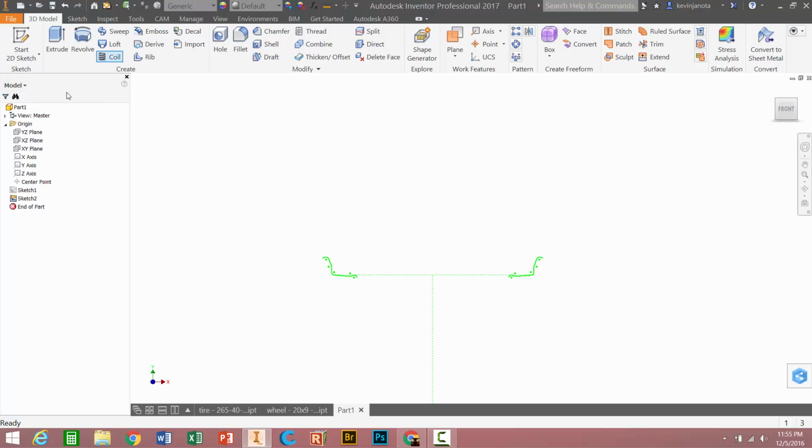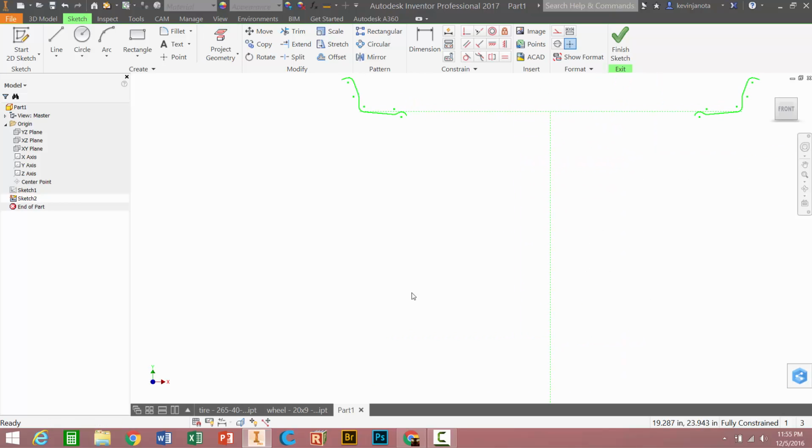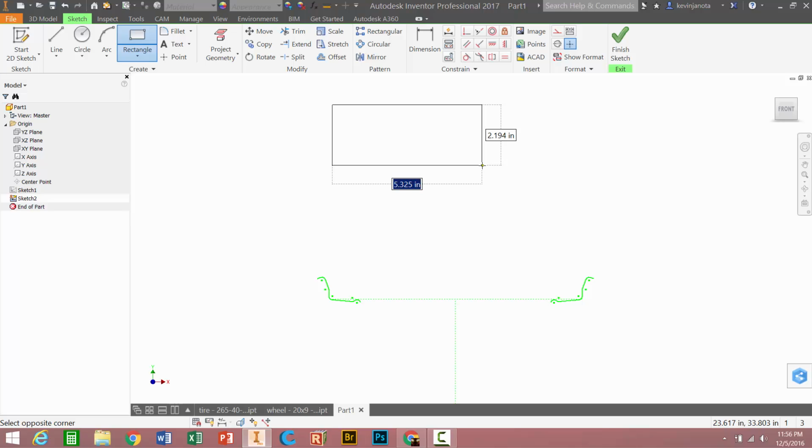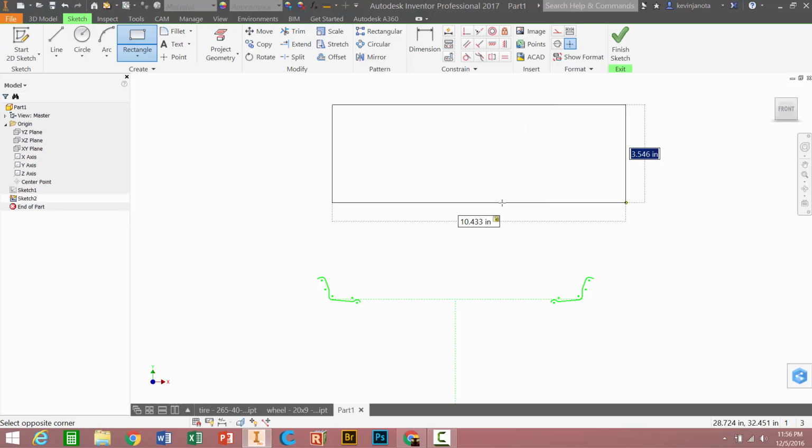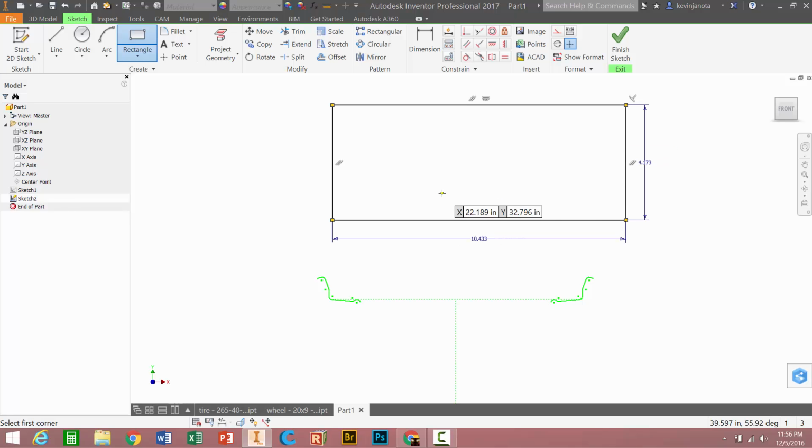So with that, the next step then is to go back into sketch 2. There we go. We're going to draw a rectangle. I'm just going to place it up here and above so that way I know it's the right size and I'm not accidentally constraining to anything below. And we want it to be 265 millimeters wide, tab, and this is going to be 265 millimeters times 0.4. Enter. And it's 0.4 because the height is 40% of the width.